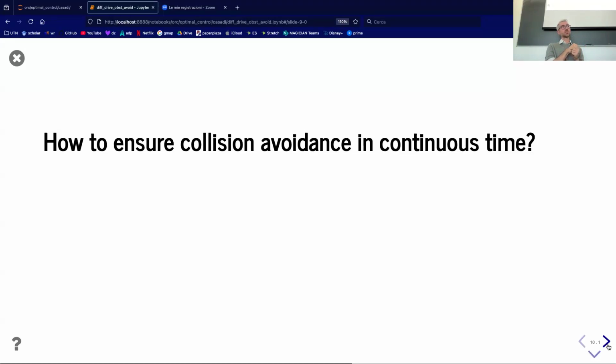Any other idea? I could increase the margin, simulate a bigger obstacle. Yeah, that's another option. So if your obstacle has a radius of 10 centimeters, well, you can say it's 11 or 12. You add a bit of a safety margin, and you hope that that margin is enough to compensate for interpolation constraints. That doesn't come with any extra computational cost.